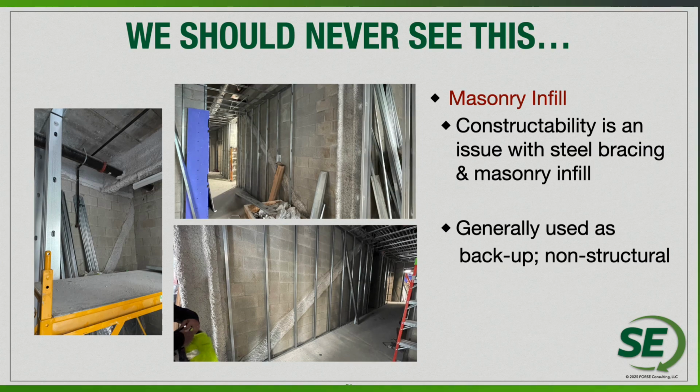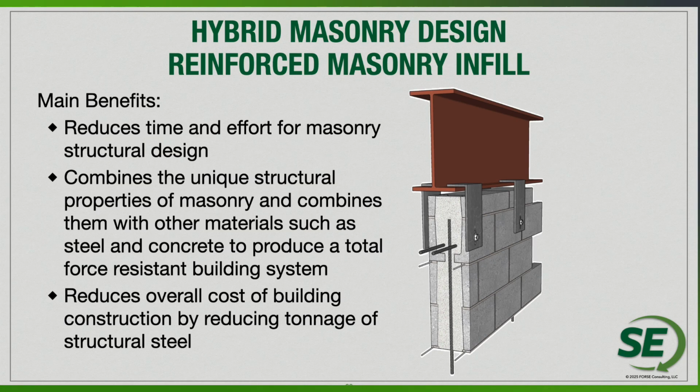So I think it's really good to understand what the masonry capacity would be, how to connect the steel elements to masonry to utilize, because the fact of the matter is all of the elements are going to be more expensive. The masonry is going to be more expensive. The steel is going to be obviously more expensive because it's there and it doesn't need to be. So all of the elements are more expensive in this design. We certainly want to take that steel out, utilize the full capacity of our masonry elements, and make sure that we have them connected.